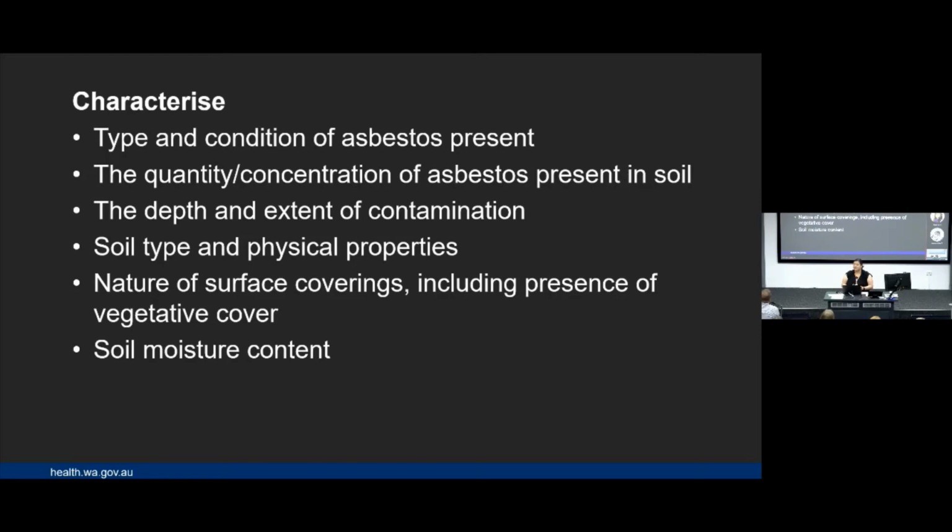If you've got sandy soils, your accessible soil level, somebody online asked how deep the occupational hygienist can deal with it. Well, if you've got very sandy soils like you do in WA, you might have to go deeper than 10 mils. You've got to look at how far normal traffic at this site is mixing this material into the soil. A step in the ground on coastal sands can go down a foot.